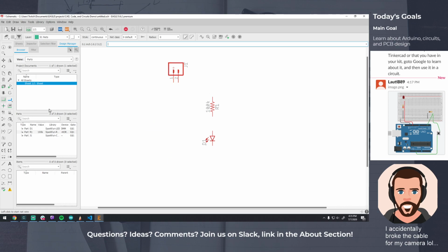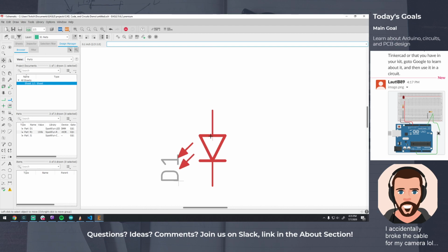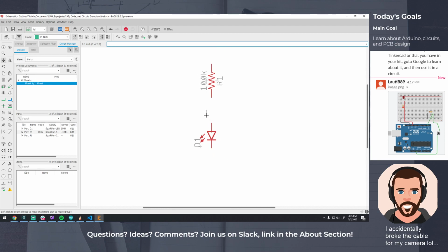I'm going to hit escape to remove that, or you can actually click on the move command, click on components. Click on components is actually a little bit confusing. You're looking for this plus that's sometimes hard to find actually. But if you don't click on the plus, you can't move the component about. So if I click on the component, you'll see it change colors, and now I can move it about. Okay, I guess it's not hovering. But if I connect the points of the resistor to this bit here, and then pick it back up, you'll see that now they are connected.